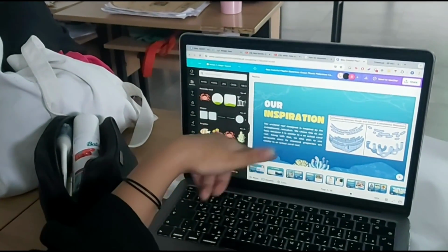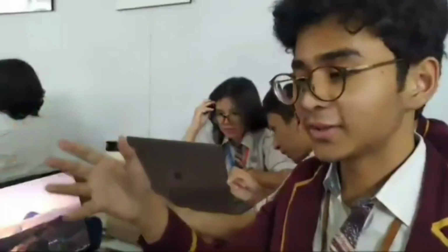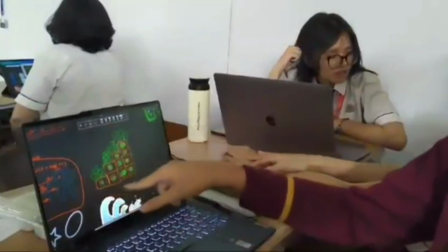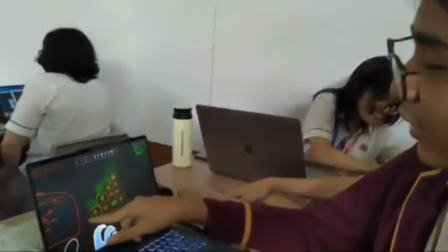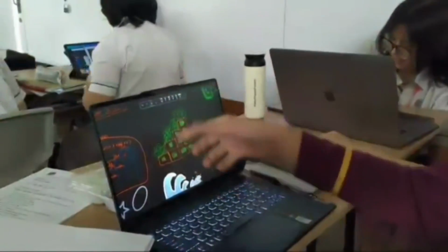You know how when air passes over a mountain, it creates extremely turbulent air. So basically, I tried to make the same design but underwater, so it'll help reduce and break the waves. So we ended up on the design of a staircase. This initial design was made by Pedro. He drew this. So we made this design so the water will come up here, and these things will absorb the energy and it'll go up, so it'll also reduce energy.